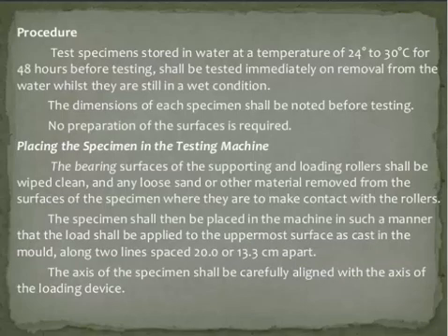So students, if we are talking about the sampling of preparing the molds for this flexural strength test, the sampling procedure will remain the same as we have discussed in the compressive strength test and the split tensile strength test. In this flexural strength test, the beam sections are casted and concrete is produced in the same manner as in the previous tests, and the specimen molds are filled with the concrete, and the specimens are cured and tested after 7 days or 28 days of curing age.